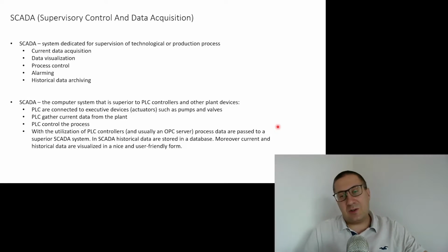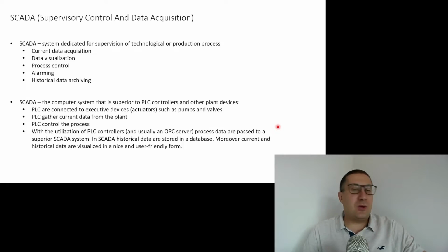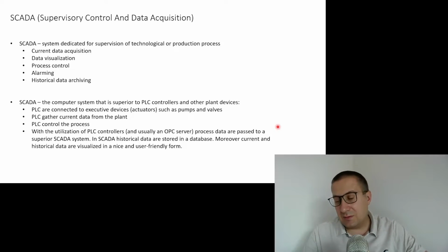He can observe trends. He can also observe alarm lists. So if there's too high pressure, he will see that he needs to react and do something, like opening the valve, for instance, if it's not done automatically by the control system.